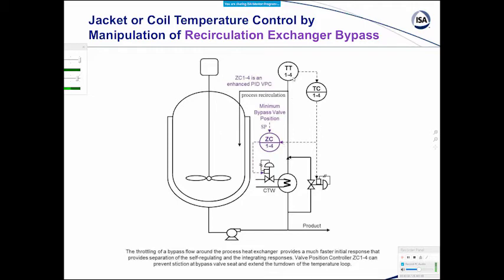And one of the challenges we get here in terms of tuning this temperature controller is that it has a self-regulating response in the short term, which is what you really want to concentrate on, and have it do its thing quickly and be tuned for that. But if you look at it long term, and particularly you have software doing this, and you have the test conducted, you do make a step change, and you have the controller in manual for maybe more than a few minutes, like an hour or something like that, you're going to see an integrating response.